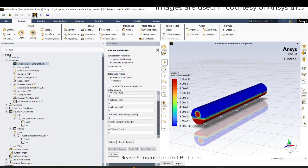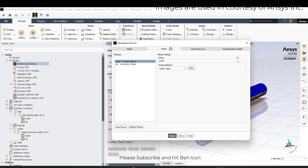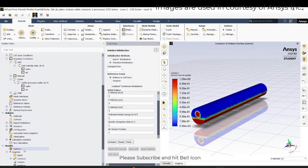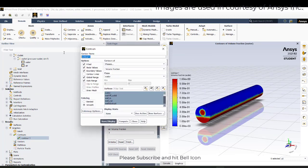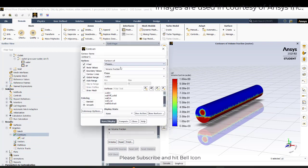Now again you can go to multiphase. Next, activate the mixture model, so it will not create any problem for you. That is the way to use the advantage of already present controls. So we have used it, and then you can go to contours, and this is volume fraction. I'll give VOF, save display, right, close.